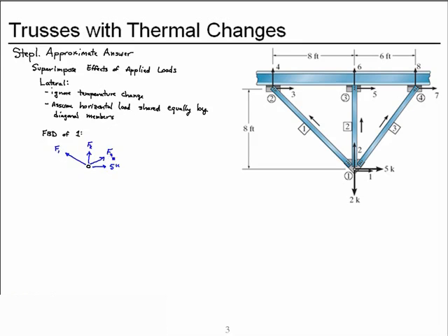And the force in member 3. And the geometry of our structure is such that we have a 3, 4, 5 triangle to describe the slope of member 3. And this is 1 to 1, so we have square root of 2 for the hypotenuse describing the direction or slope of member 1.